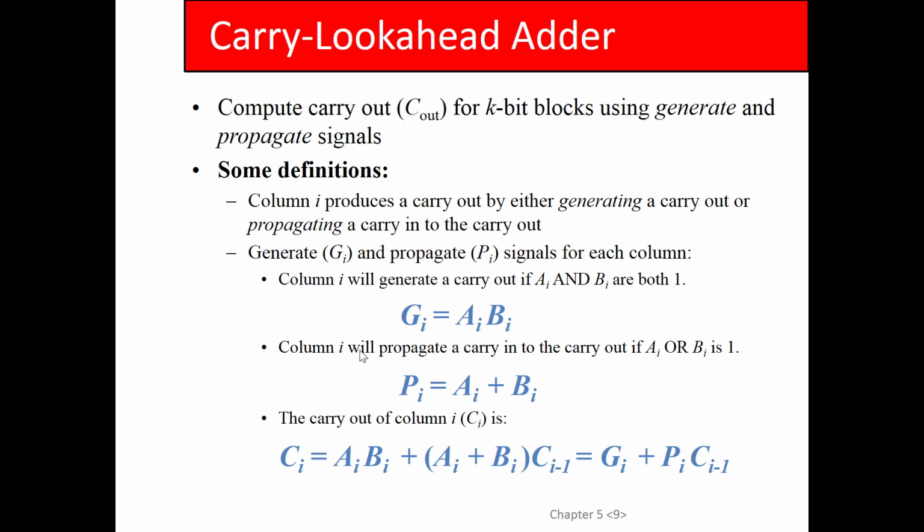The problem here is that we want to try to make the carry chain shorter, essentially. The problem is in terms of gate delays, by the way. You've got a carry in, it goes into the first adder, propagates through the first adder, becomes a carry out, then goes into the carry in of the next adder and goes through that one and becomes a carry out.